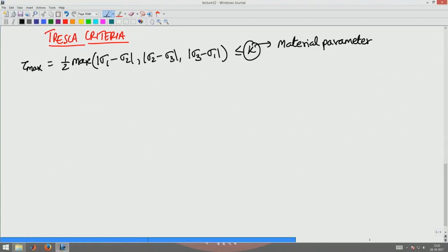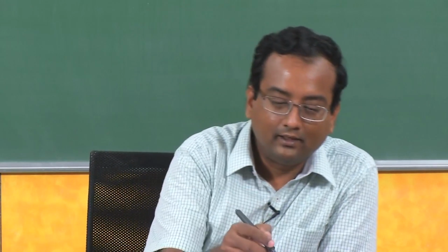So, how do you find this material parameter? You have to do some experiment to find it. Typically, we have been using uniaxial experiments to find the Young's modulus and Poisson's ratio. So, we will use the same experiment to find this parameter. Let us say the body began to yield or fail when the uniaxial stress reached sigma y, called the yield stress of the material.